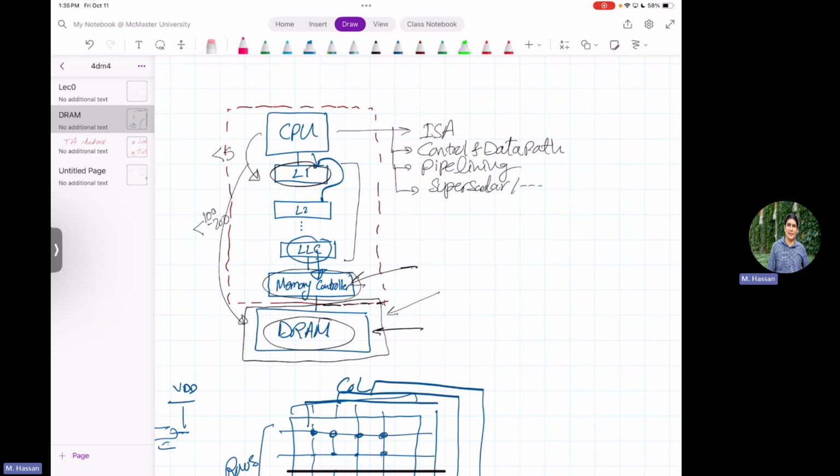But associated with the memory controller is something called a DDR5 PHY, which is your physical IP that is responsible for things like clock domain crossings, handling the correct electrical domain and voltage levels, termination, analog and mixed-signal stuff, right? The idea is, yes, the memory controller has to handle clock domain crossings correctly, because you are receiving data at one speed, and then you have to transfer it to the LLC at a different speed. So the memory controller is usually divided into two parts, front end and back end, and these two are working at different speeds.